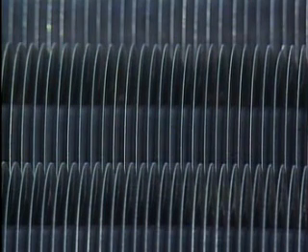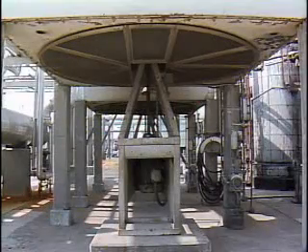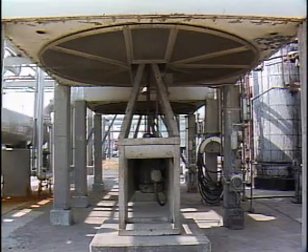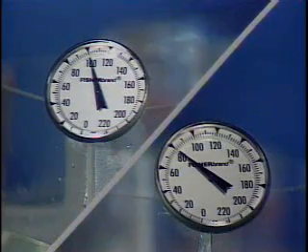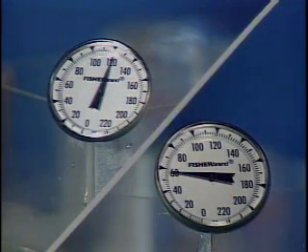The fluid transfers heat to the tubes by conduction and convection. Some of this heat is then transferred through the tubes and into the fins by conduction. From there, heat in the tubes and the fins is transferred by conduction and convection to the surrounding air. To increase the amount of heat transferred to the air, the fans in the cooler can be started. This increases the airflow through the cooler, which increases the amount of heat that is transferred by convection to the surrounding air. For example, as the difference in temperature between the two fluids in a heat exchanger increases, the amount of heat that can be transferred also increases.